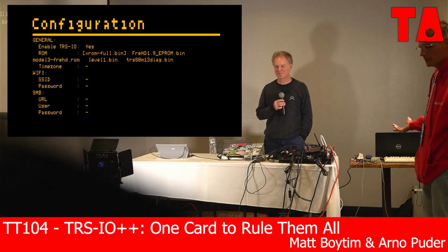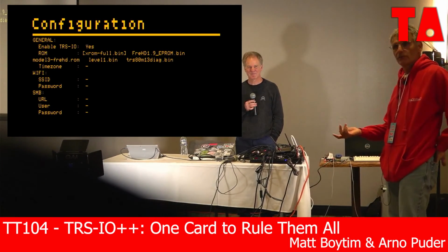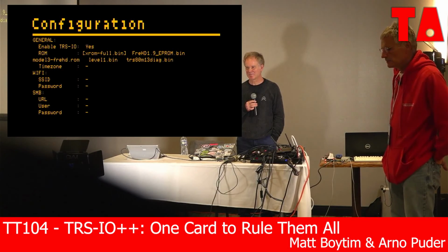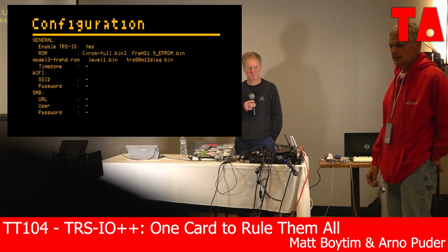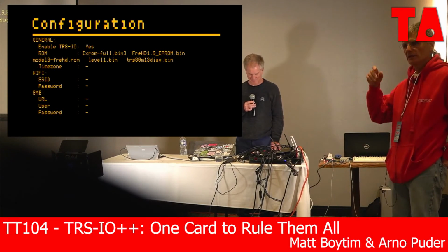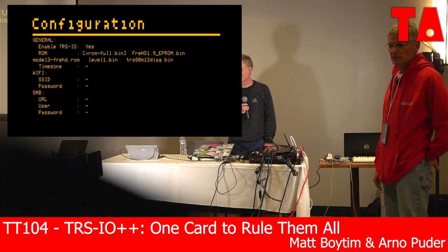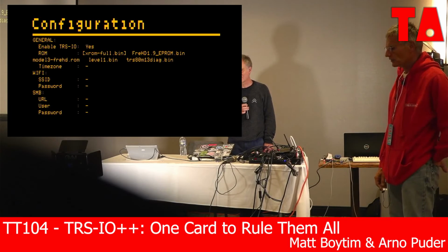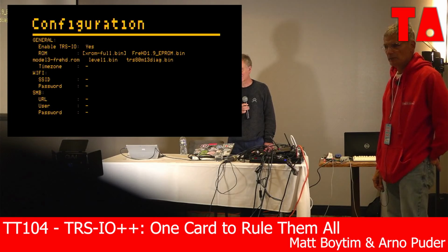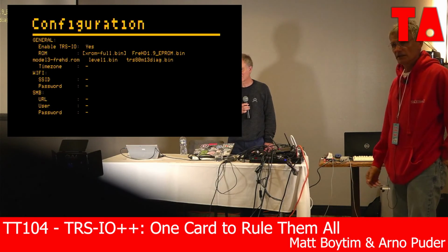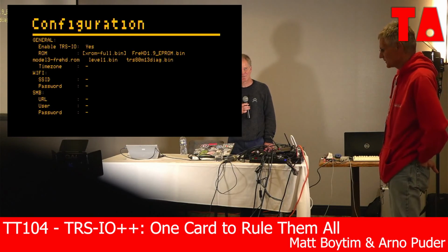So this particular module is really intended for RISC-V development. You can implement, and in fact, they have examples with the RISC-V in it. Then you would have the cache controller, and you'd be able to make use of that SDRAM, and I think they have execute in place from the serial flash. I don't know what kind of performance you would get from it, and how many resources. If it tied up a bunch of that block RAM to implement the cache and stuff, then you wouldn't have that available for the Z80 emulation, the TRS-80 emulation.